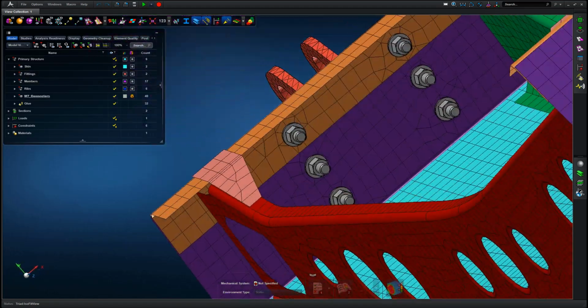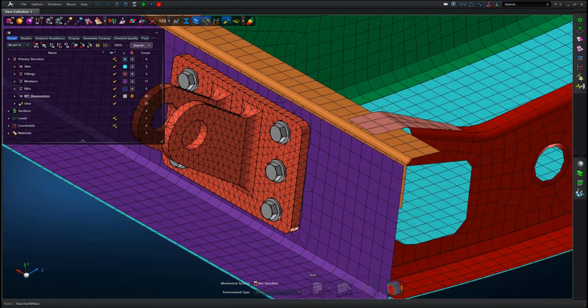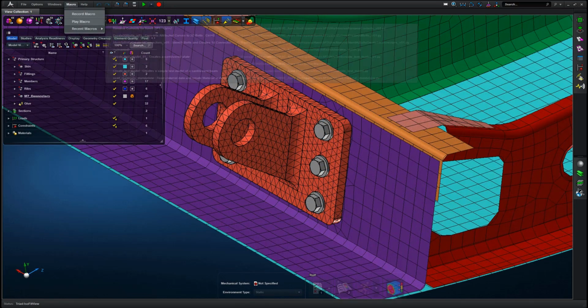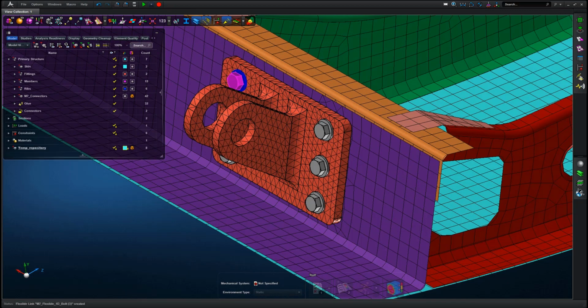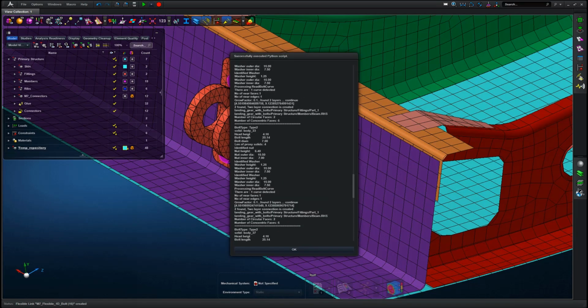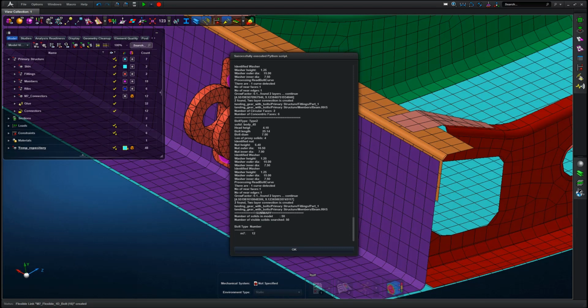Okay, so moving on to a second example, and this one looks at a bolted joint. So again, fastener related, but we are now using a script to find CAD geometry that resembles a fastener definition. In this case, the features that make up those CAD definitions are recognized within the model browser tree, and then we get the summary table to show what's been found.